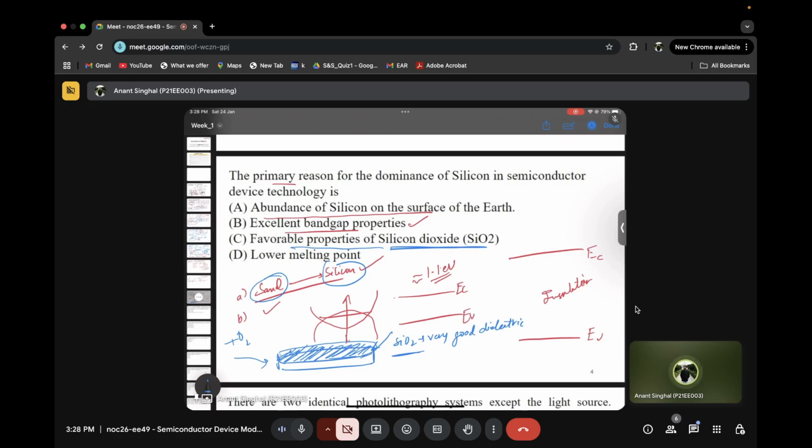So just by the reaction between the oxygen and the silicon, we have a grown SiO2 over it, which is very uniform in nature. We cannot have a very rough surface because that will not have very ideal current, or that will have very unrealistic effect. So we need to have a very smooth surface, right?